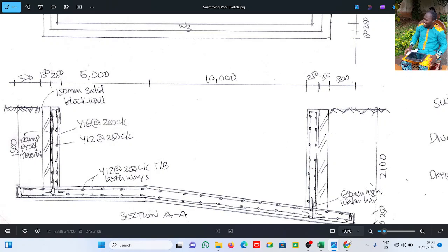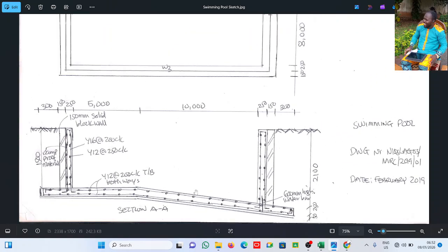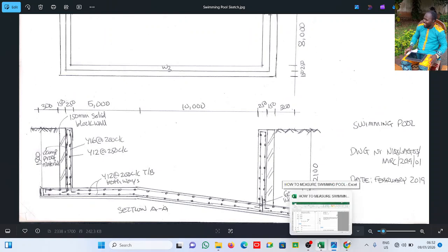One is the cover, which is 50 we used, and then before the bending, it goes maybe 100 mm, and then you add the bend. I don't think it is allowed for. So if you're doing work professionally, or maybe an exam, please remember that it is not in. I didn't add that little projection, maybe 100 mm. It may be minute, but at least for professionalism's sake.